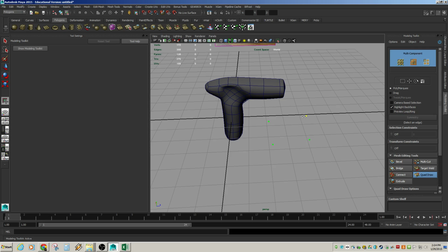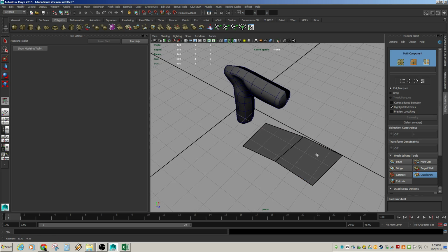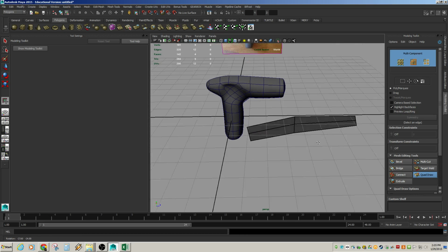And you can see that it's going to allow me to draw on the grid, and if I just click those 4 points, then it's going to make these 4 points, click 2 more, whatever. But if I hold shift, you can see that it'll allow me to turn that into a face that is a quad, right? Now, I can middle click on any point and move this stuff around. I can actually shift right click and paint some smoothness to it. Or I can hold control and insert another edge loop, right?